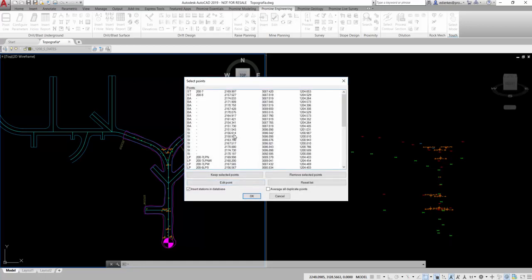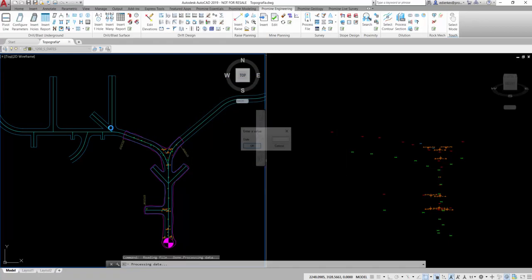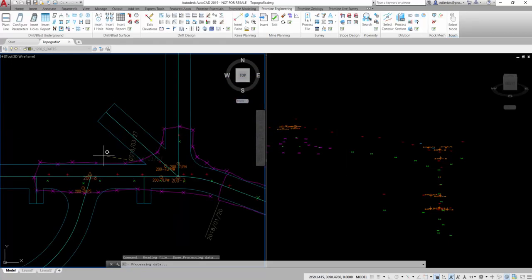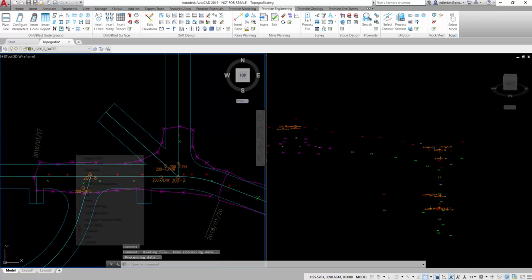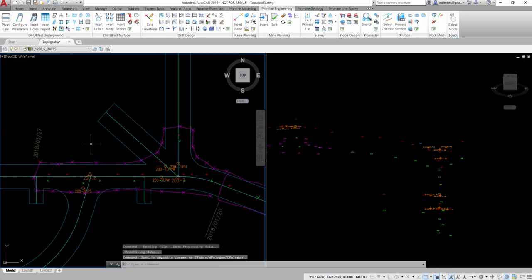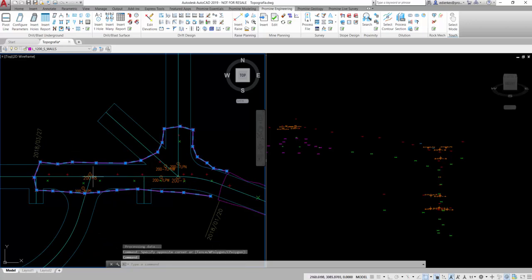Selecting OK, the file information will be processed and can be viewed and edited in the following window if it is necessary. We are just indicating that we want to add the stations to the database and finish the process with OK. We're quickly inserting the date of the survey, and now we can see the newly added survey points in the drawing. With this new part, we can see that the different types of points were already sorted into distinct layers, and based on their types are represented by different pre-configured blocks.